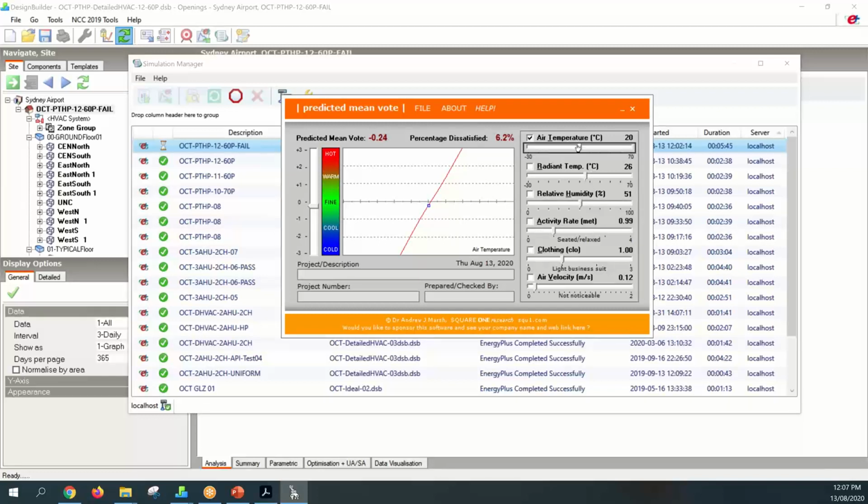And what we'll see is that we are being asked to maintain an air temperature of 21 degrees, but typically your radiant temperature will be less than that. So unless you maintain a radiant temperature which is close to the air temperature, which means your fabric needs to be pretty good, you will very quickly fall below the -1.